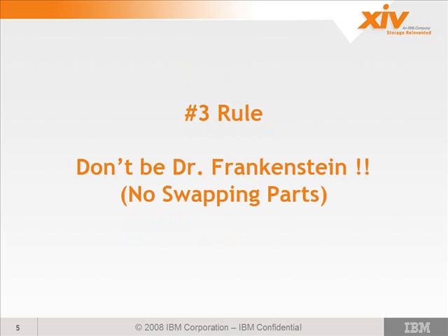Rule number 3, don't be Dr. Frankenstein. Don't go swapping parts in this box. You don't want to create a monster, okay? You may think, oh, this is working fine. I have a failed module, I'm just going to swap this part in. I'm too lazy to put in a whole thing. I just want to put in a new FSP instead of replacing the whole module.